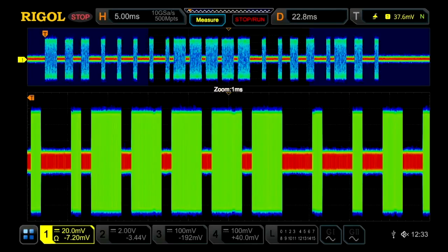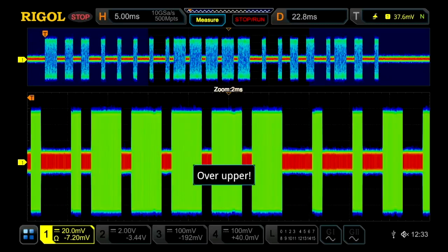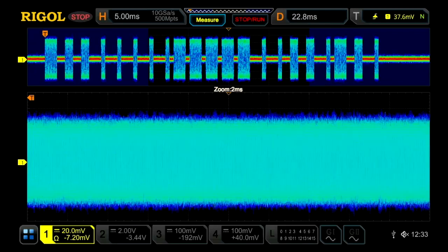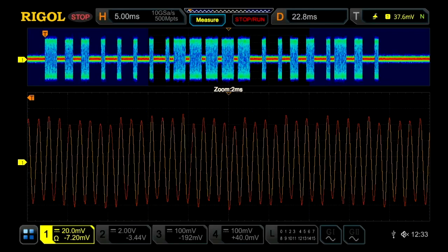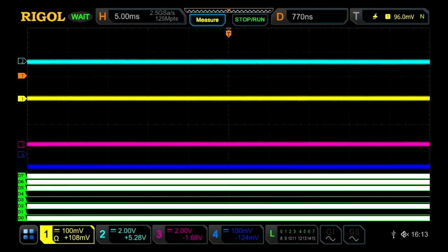And then, of course, we can zoom in and really look at all the detail because we have 20x oversampling on all those pieces. So we can go ahead and zoom all the way in down to nanosecond range. It's pulsing on and off. And we can see that with more than 20x oversampling on each signal while still capturing an entire 50 millisecond pulse sequence. So it's a great way to use the high sampling capability of the 7000 with the deep memory together to really be able to analyze the full signal.